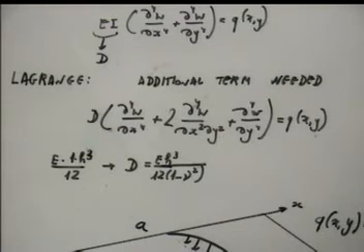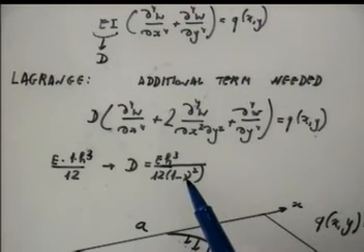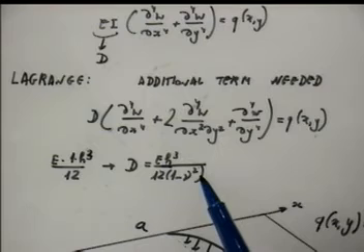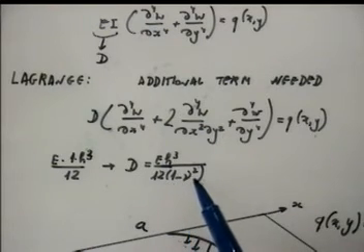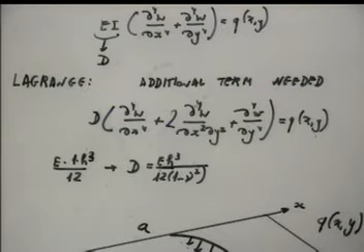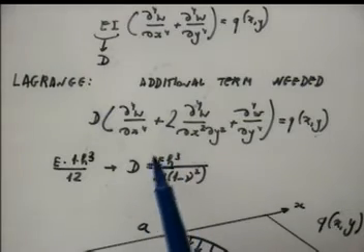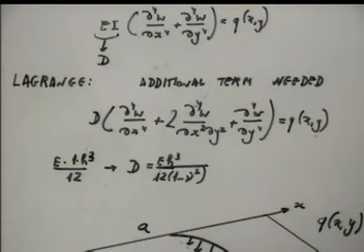If you are pulling in x direction, then in y direction something happens, and there is Poisson effect. So plate equation does have this, and that comes as 1 minus nu square. But this effect is not very big, because if nu is 0.3, then nu square is 0.09, 1 minus nu square is 0.91, so approximately 0.9, which gives just an increase of flexural rigidity by about 10%. Nothing else.